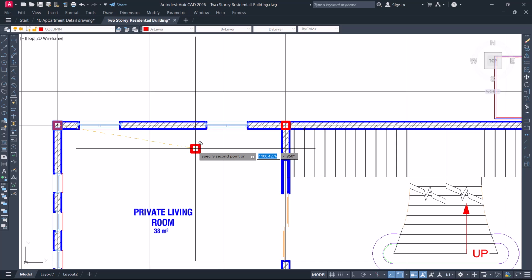Now, when you begin to exceed 6 meters, for example, you are at an 8 meters span beam, 10 meters, you will see that you'll be having issues in deflection. So you have to design the beam against deflection. In turn, you will have to increase the depth of the beam a lot. So just to avoid that, maintain that your beam span or your column spacing be less than or equal to 6 meters. That will also help you when you are performing your slab paneling.